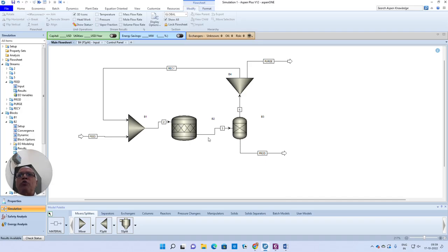We know the input to the reactor model along with its equipment parameters and operating conditions. We should be able to solve this model to calculate stream 3. And again, once we know the input, we will be able to calculate the product stream and stream 5 by solving this model. Similarly, once we know the input, we will be in a position to calculate purge and recycle. Remember, we started with an initial approximation for about 5 variables. We were able to get an updated set of values for the recycle stream. Check whether you have come to a convergent solution. Otherwise, a new recycle value is taken and the process is iterated, right?